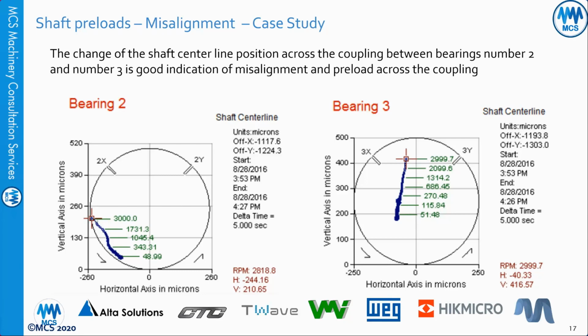So when your shaft is running with a high eccentricity ratio, the stiffness will increase, the damping will increase, and this is what we need to focus on, and the fluid instability will decrease. When you have a low eccentricity ratio, like if the shaft is running near the center, the fluid instability will increase, and the chances of oil whirl will increase, but the stiffness will go down and the damping will go down. That's very clear.